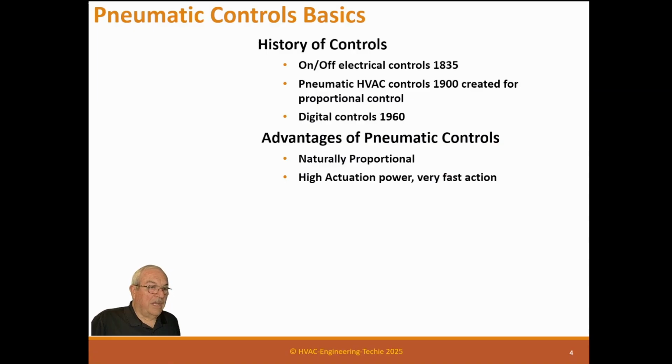You can run 85, 125 PSI, and you can move some big valves and big dampers because you have so much force. They are very fast acting. Now, remember that most electric actuators are all motorized, and they take time. Like 30 seconds is a fast actuator. 15 seconds is a really fast actuator. But that's not very fast.